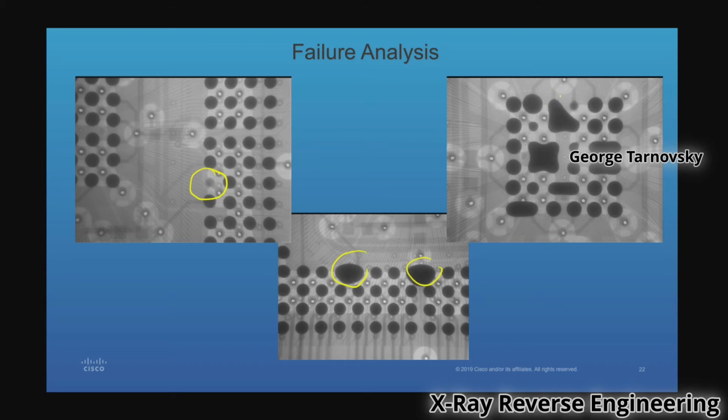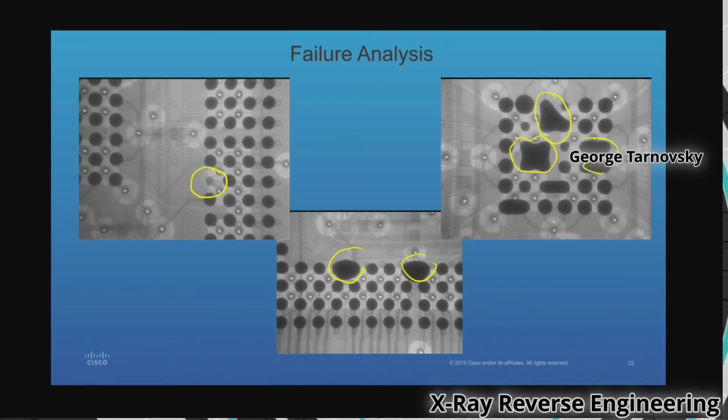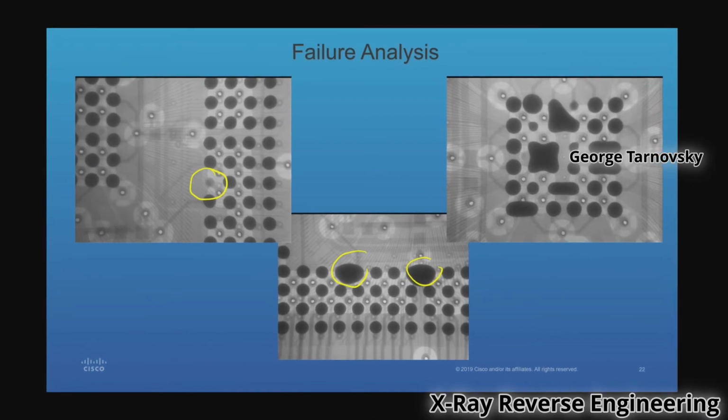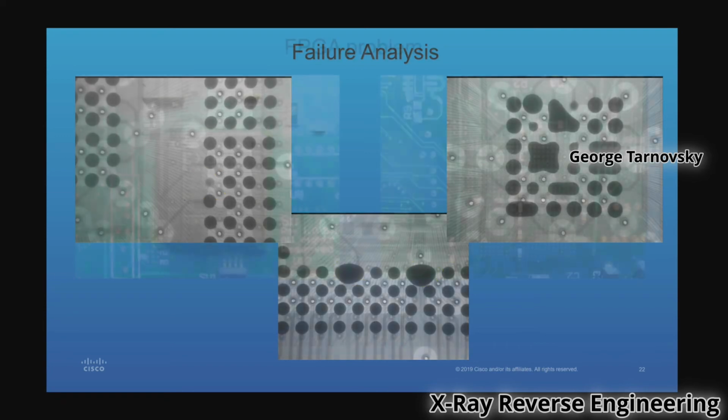It's a real problem. So you've got 3 shorts here, you've got 4 shorts here. I mean, this is a mess. In any event, the X-ray, before you power it up and destroy the circuit, or some of the BGAs, we've got BGAs we paid tens of thousands of dollars for. You plug it in and destroy it, it's very painful. So consequently, the X-ray helps you to ensure that everything is correct.